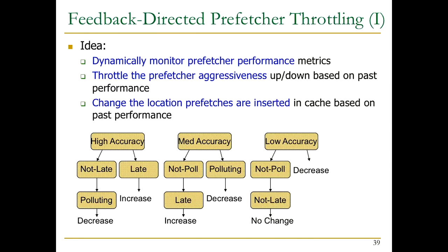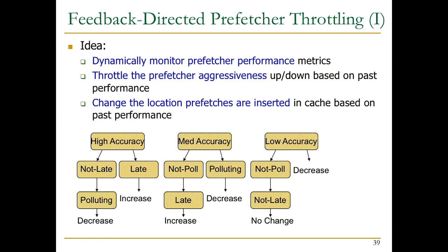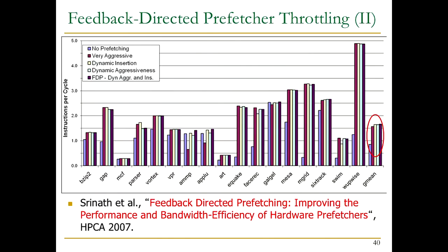So clearly, like with any other threshold-based mechanism, this is prone to thresholding errors. And also, there are a lot of design choices here. How do you determine these choices? So these kinds of things are actually good for looking into learning-based algorithms to learn over time. Because there's a lot of data that's input into the prefetcher from many, many workloads over time, right? If you think about a single nanosecond, you're actually getting a lot of requests from different cores. OK, so if you do something like this, well, you can read what that full thing is from the paper.